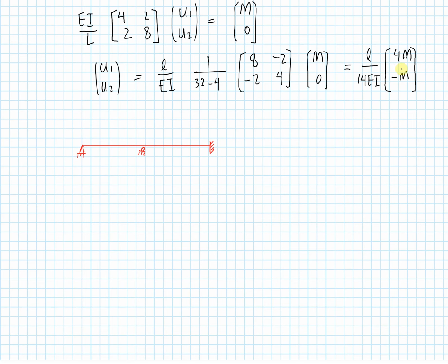And I'm looking at the magnitudes, and the first one is 4 times the other one. So I'm going to draw a deformation that is truly representative of that magnitude. So that'll be a 4, and this one will be tinier, so that's going to be 1/4 the other one, and it's in the negative direction, so it's rotated clockwise.